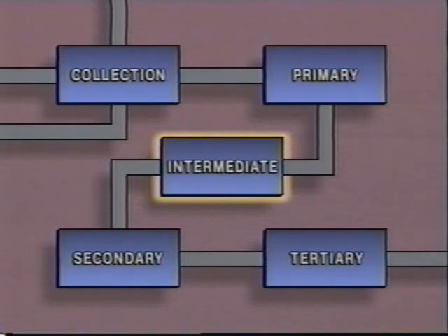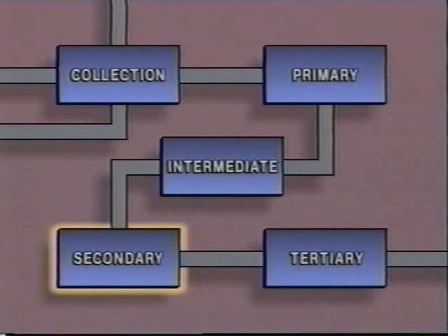The purpose of intermediate treatment is to eliminate dissolved and finely suspended solids. The next stage of the system is secondary treatment. In this stage, organic material is decomposed and removed. Organic matter can occur naturally, or it may be a result of industrial operations.